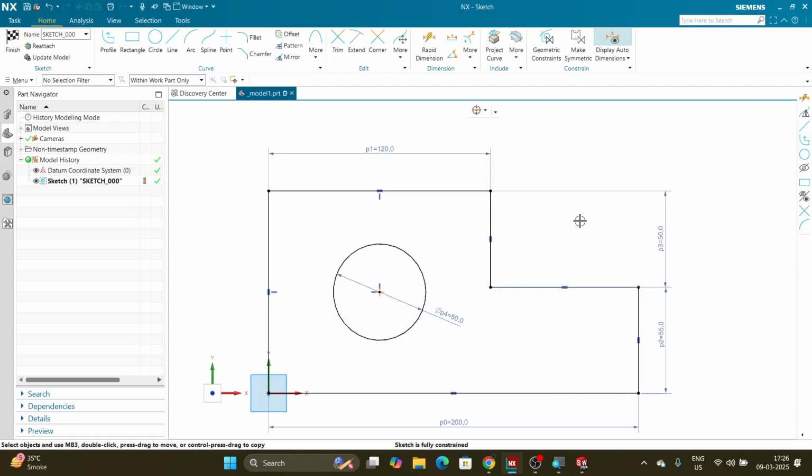And if I force it to be equal, it will not accept it. Now let's try. See, yeah. So to make an equal relation, I need to pick the line first. Now, sometimes what happens is we have an overlapping geometry here, or let's say multiple geometries here, and it is very difficult to make the selection sometimes.